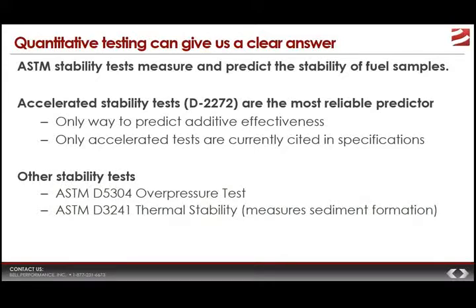Now quantitative testing is essential because it's the only thing that will tell you from a measurable level what condition the fuel is in right now, and it's the only way to really be able to predict with any kind of accuracy basically how much longer you have before that fuel is going to go bad.